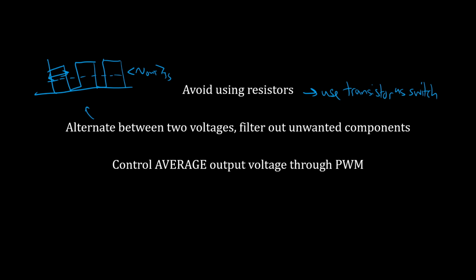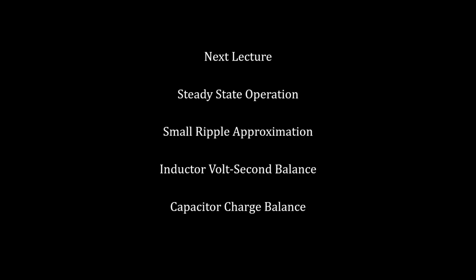Right? So this is a unique way of analyzing a switch mode power supply. Even if you weren't studying power electronics, you could conceptualize how to do this. Someone studying signals or analog electronics could think of this as well, right? We create a square wave, we filter out high frequency components and keep the DC. Super simple, right? But not every converter can be analyzed in this way. And we're going to need a different set of tools to analyze them.